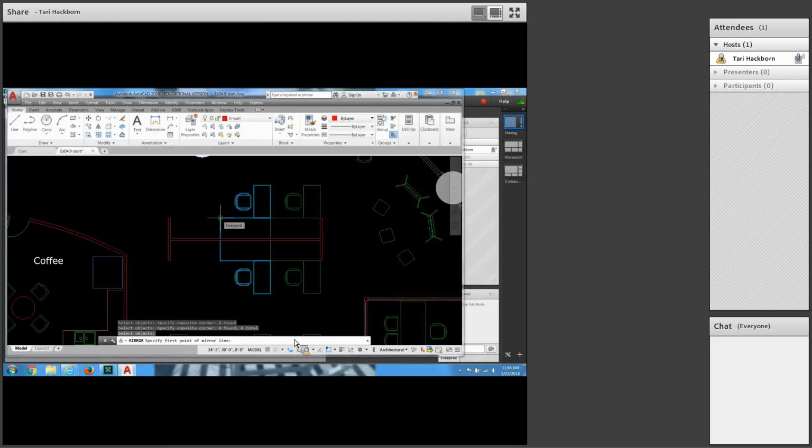The illustration down at the bottom says click this point A. Point B is clicking anywhere that is right straight above this line. So apparently I have to turn ortho on again because it's not on. So let me turn ortho on and come up here and click any point and then press Enter so that command is ended. And there's one more